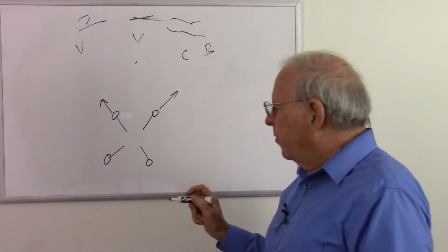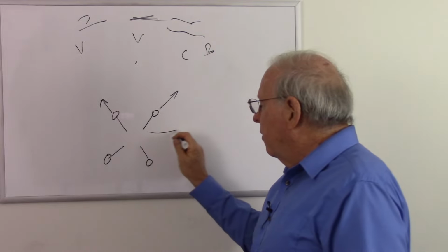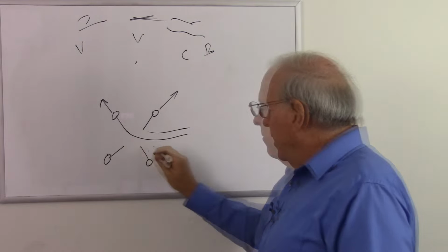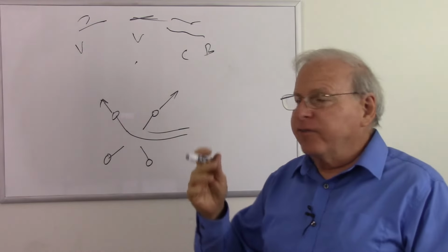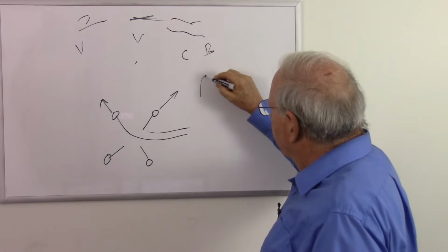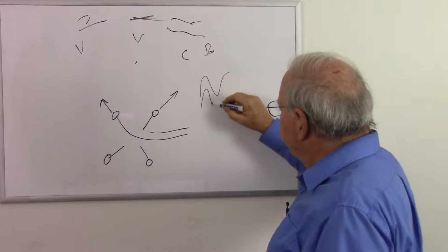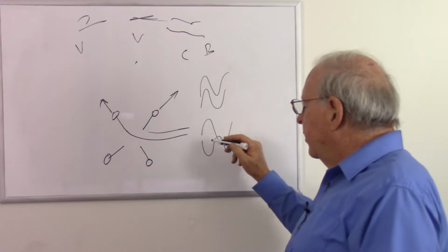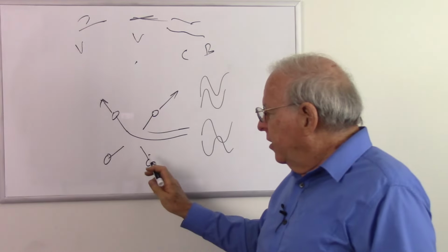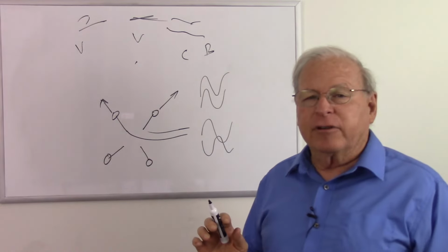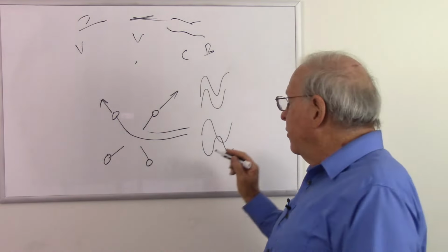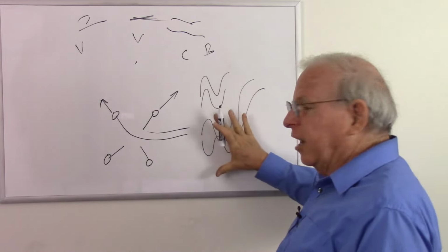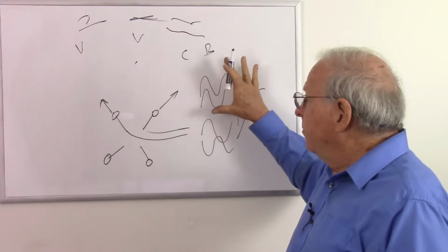So there's our microphones pointing to the back, and these go into our mixer normally, but of the 2 back channels, one has its phase flipped. So the 2 front channels are going in phase, the 2 back channels are going in out of phase. And this, of course, is done in the mixer, and what that does is sounds coming from the back actually get canceled out. But what we can do is mix those in to these 2 channels. So those 2 channels in the back are canceled out and you can't really hear them in the front.